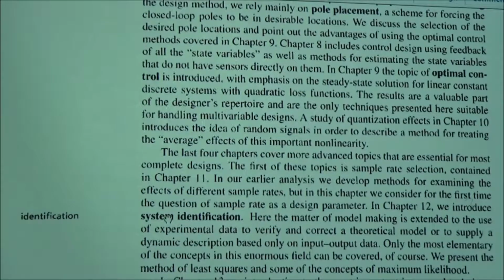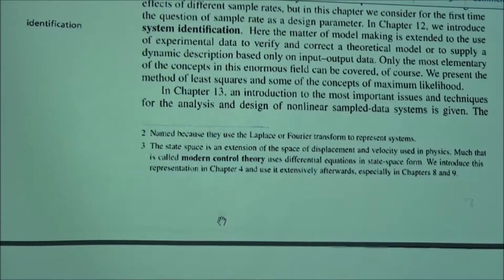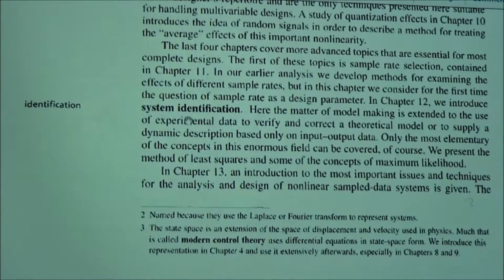Basically, when you have input and output information of a plant whose model is not quite identified for you, you could use a system identification approach to come up with a model for that plant, which otherwise would be like a black box. So again, those are also available. In MATLAB, there is a System Identification Toolbox.